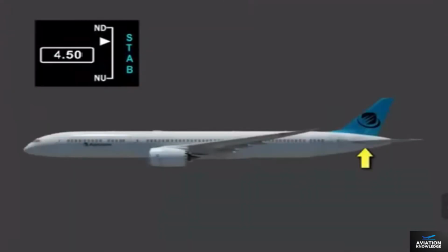If uncommanded stabilizer motion is sensed, the stabilizer channel that caused the motion is automatically shut down. If a channel is inoperative, the ICAS advisory message, stabilizer L2 or stabilizer R2, is displayed. The stabilizer remains operative through the remaining channel. If the affected channel cannot be isolated, both channels are shut down. If both stabilizer channels are inoperative, the ICAS warning message, stabilizer, is displayed. This warning is also displayed if the automatic shutdown fails to stop the uncommanded motion.